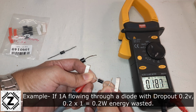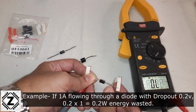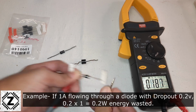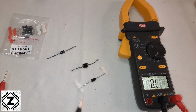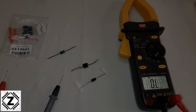Even if we round it up to 0.2 volts multiplied by 1 ampere, the same equation that we used over here, if 1 ampere current is flowing through this, the amount of wasted energy is going to be 0.2 watts. That is less than half the amount of energy that this one was wasting. So that is the reason we generally prefer using Schottky diodes in SMPS type power supplies.